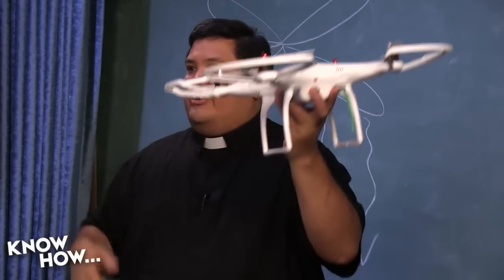And you'll exit the VRS, because that seems like it would be a very natural reaction, is to just give it more throttle. You're starting to go down, give it more throttle. Yeah. And the problem is, you don't always enter VRS. You're not always in the vortex ring state when you're coming down. So sometimes goosing the throttle will help. In fact, that's how you land.